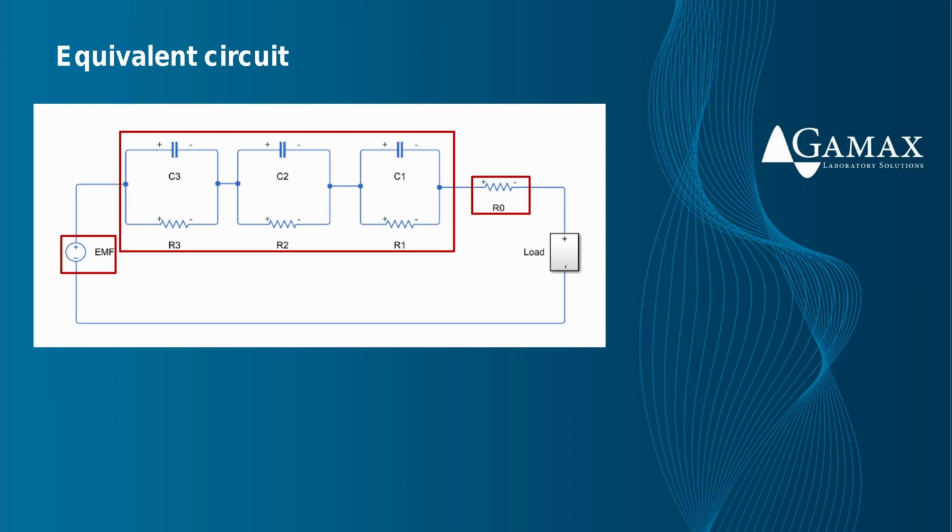When modeling a battery cell using any given circuit, it is important to choose circuit topology and parameterization such that it can respond as similarly as possible to a physical battery cell. A typical equivalent circuit includes the voltage source associated with the open circuit potential, a series resistor related to the ionic conductivity of the separator and the electrolyte, and one or more RC pairs that represent the processes involved in the intercalation and deintercalation of lithium ions in and out of the electrodes.